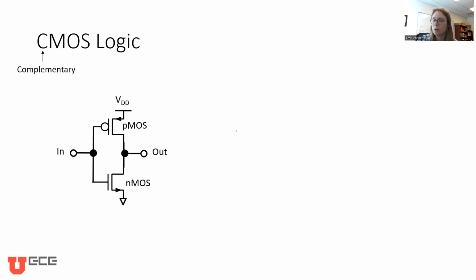So let's go look at how actual modern computers implement this. CMOS stands for complementary MOSFET logic. And it's called complementary because we have both flavors of MOSFETs, the PMOS and the NMOS. And so let's see what this circuit does. Again, using this whole idea of binary, I can input a logical 0 or a logical 1. A logical 1 will be 5 volts. And then let's look at what we get out in each case.